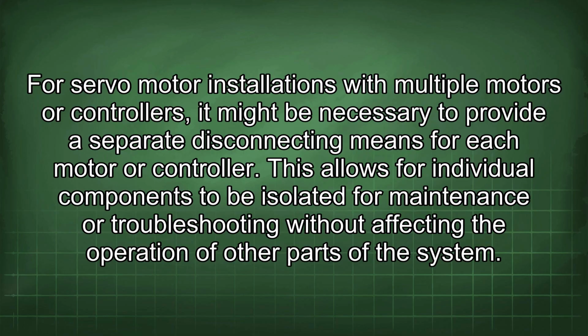For servo motor installations with multiple motors or controllers, it might be necessary to provide a separate disconnecting means for each motor or controller. This allows for individual components to be isolated for maintenance or troubleshooting without affecting the operation of other parts of the system.